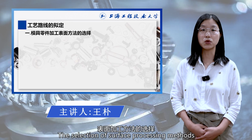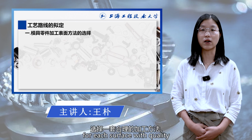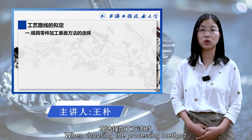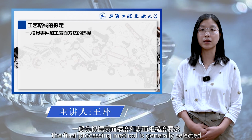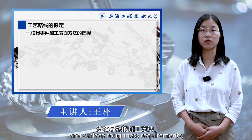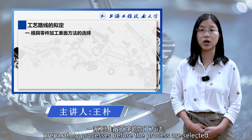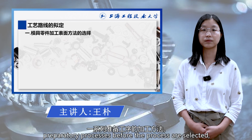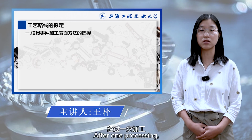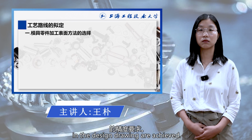The selection of surface processing methods is to choose a reasonable set of processing methods for each surface with the quality requirements on the part. When choosing the processing method, the final processing method is generally selected based on the surface accuracy and surface roughness requirements, and then the processing methods of the series of preparatory processes before the process are selected, and the order before and after is listed. After processing, the precision requirements specified in the design drawing are achieved.